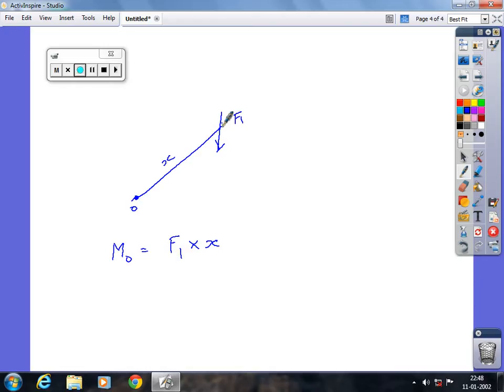So what you'll have to do is extend or draw the line of action of the force so that it will be a line like this. Do you understand? And now you can mark the perpendicular distance from here to here, and if this is equivalent to x1, then the moment of this particular force with respect to the point is equivalent to F1 into x1. The first is wrong, and this is going to be correct. Have you understood? See, I told you, moment is defined as force into perpendicular distance. Very good, right? Moment is defined as force into perpendicular distance.